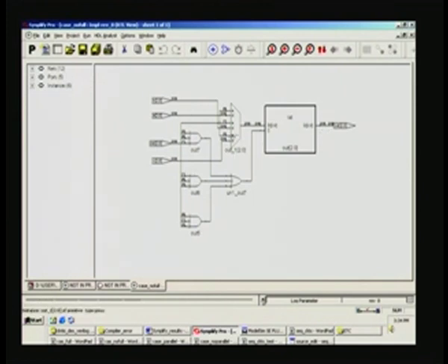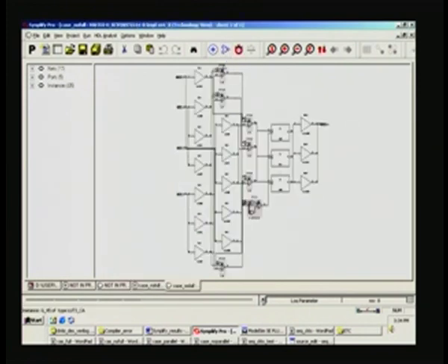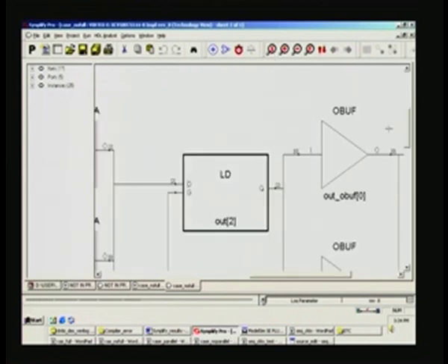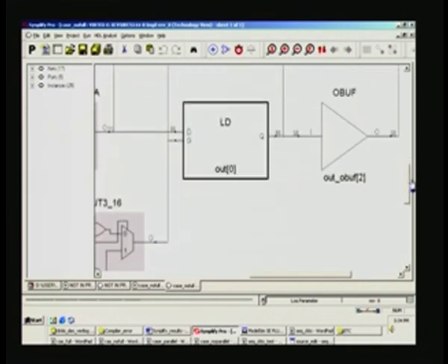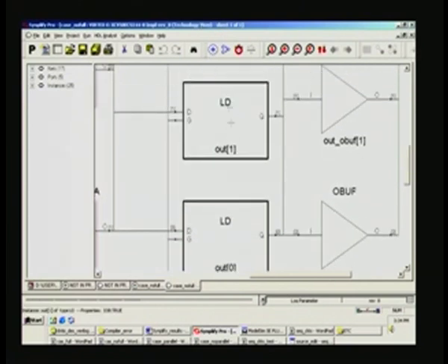So, that is quite a substantial saving, and if you also view it once again, it is the same 2 plus 2, 4, then 6 here, one extra LUT has come over here, and again the count of input buffers and output buffers may essentially remain the same, and only this has made a difference, and plus you see the latches here. See, all LDs are all latches, 3 additional latches have been created. So, only if you look into the technology view you get the real story behind that.